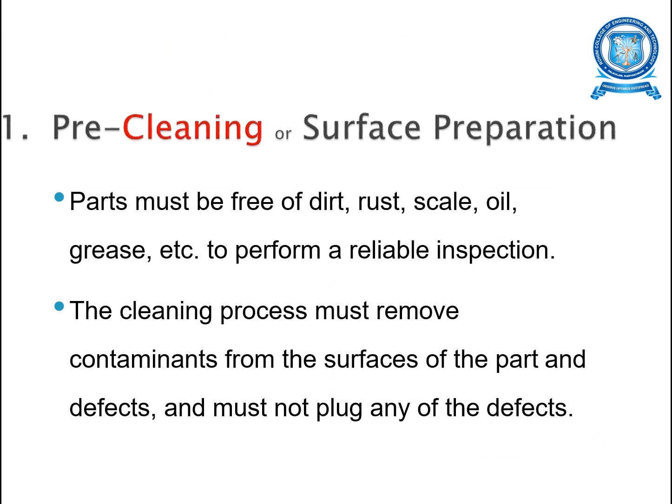The first is the pre-cleaning or surface preparation. So normally the parts must be free of dirt, rust, scale, oil, grease, etc. to perform a reliable inspection. So this process is to remove the contaminants from the surface of the part and the defects.